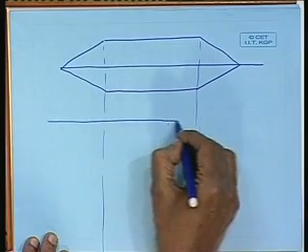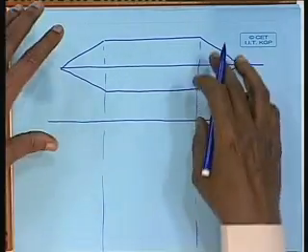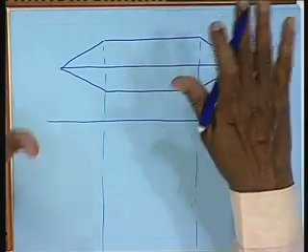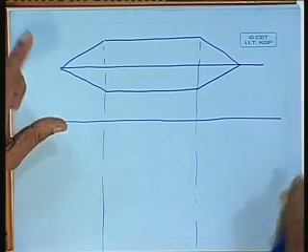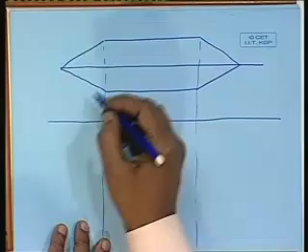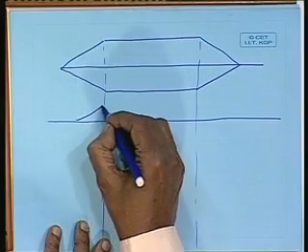First, he said that there is a constant pressure distribution around the hull shape. Actually, he said there are 5 wave systems. We have seen here 4. There is a 5th one, a wave which as if stays with the ship, does not move, and does not take any energy, but a basic pressure difference develops because of the shape of the body, and such a pressure difference is the one we had seen before.